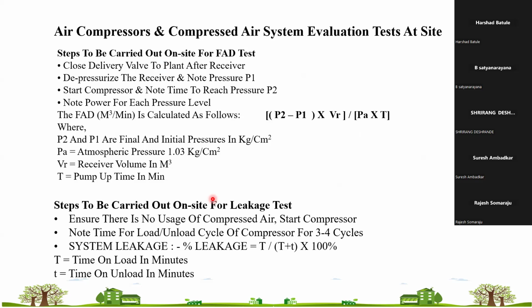Multiple efficiencies are calculated, but your main efficiencies are isothermal efficiency and volumetric efficiency. But apart from efficiency, your main practical term to evaluate the performance is the specific energy consumption of the compressor.